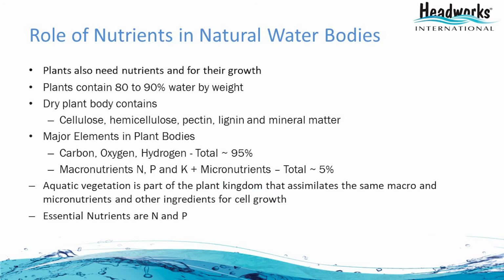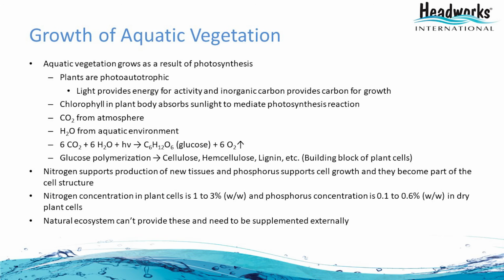A discharge of these nutrients in an uncontrolled manner to the receiving water bodies can lead to the growth of such aquatic plants, which create nuisance odors, poor health of the water body, and make the water unsuitable for beneficial use. The aquatic vegetation we were talking about is photoautotrophic, which means that for their growth, they extract energy from light.